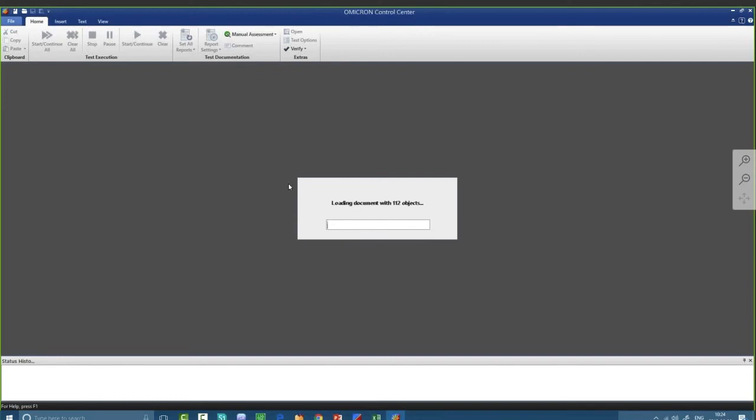You will follow the same steps, except we have to select the proper compatible format for that setting. In case of SEL, we need to use TXT. In case of GE, we need to use CSV. ABB, Siemens, Alstom, Schneider, all are supported by XRIO.